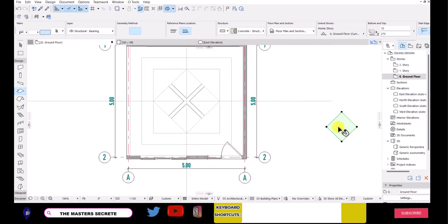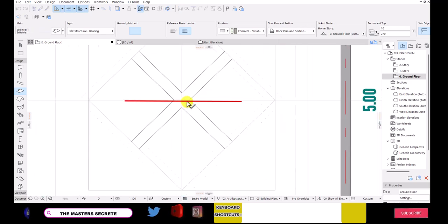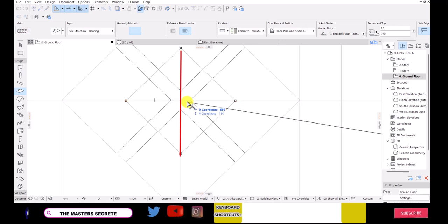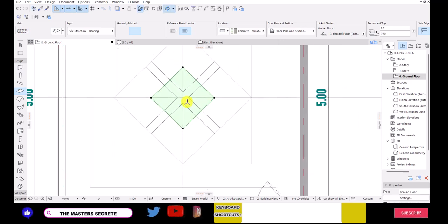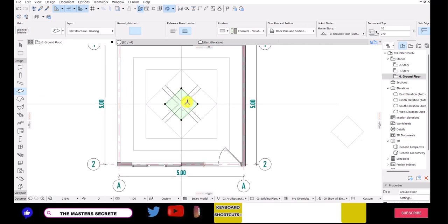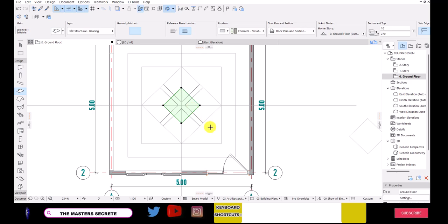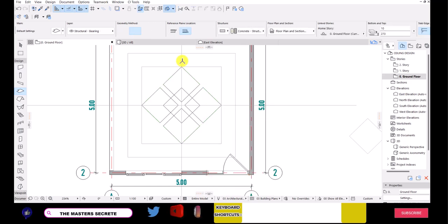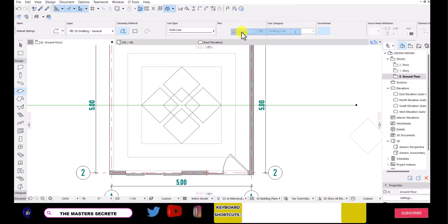Now we are going to drag this one, Control D to drag it and place it at the center of the lines, of these lines, and this line of the horizontal and vertical line. Place it at the center. So that's it. And now we're just going to eliminate all these other lines which we use as reference. Going to eliminate it because we no longer need it again.